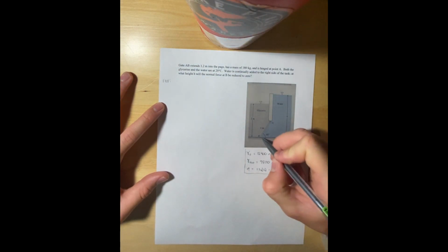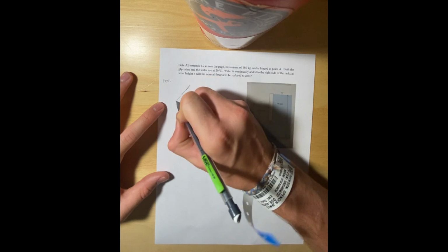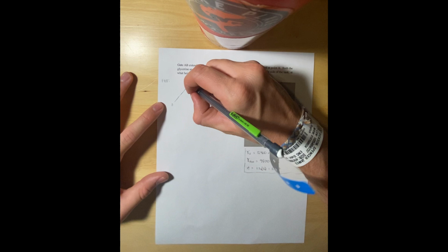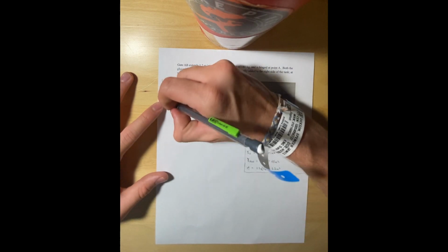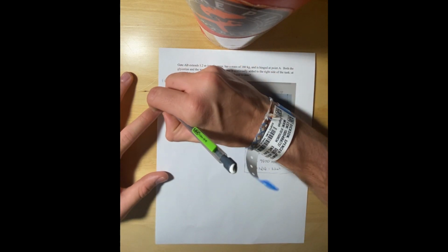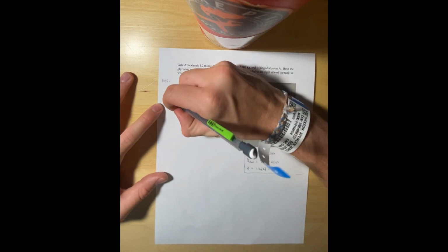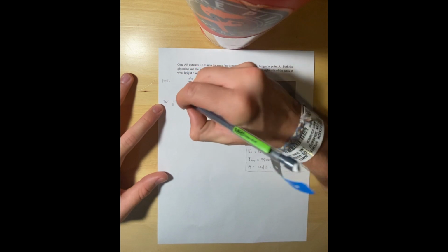All right, so we're just going to do the free body diagram of this gate right here. Draw it out like that. This is going to be point A, this is going to be point B. So at point A, we have A sub Y and A sub X, like so. Here we have force B sub X acting. The gate, we're going to do this as 60 degrees. All right, so we have two forces, or three, I guess. Main forces acting on this.